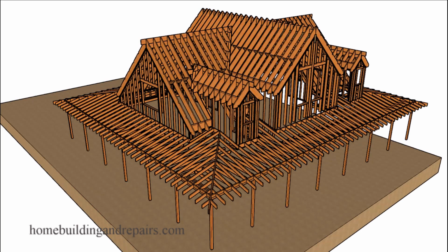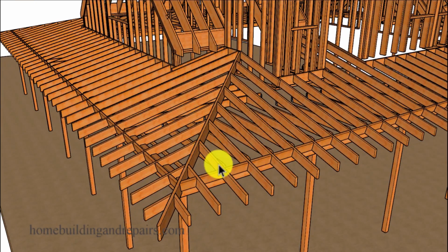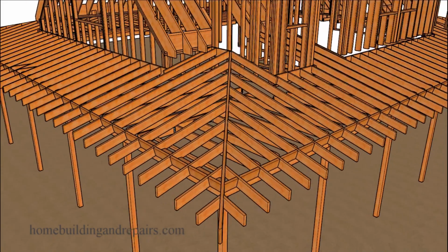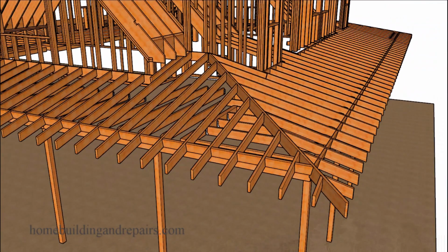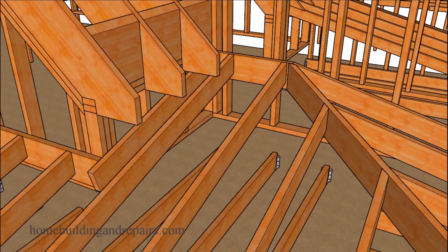Let's go ahead and remove the fascia board and then come in on the front corner of the porch here. And in this model, I spaced all of the rafters 16 inches on center and tried to make it work out for the plywood. So I kind of went 16 inches on center all the way through in both directions if I could. Zoom in on this part of the house where we're going to have a full-length rafter and a partial rafter that's going to nail into the wall framing along with our ledger here.